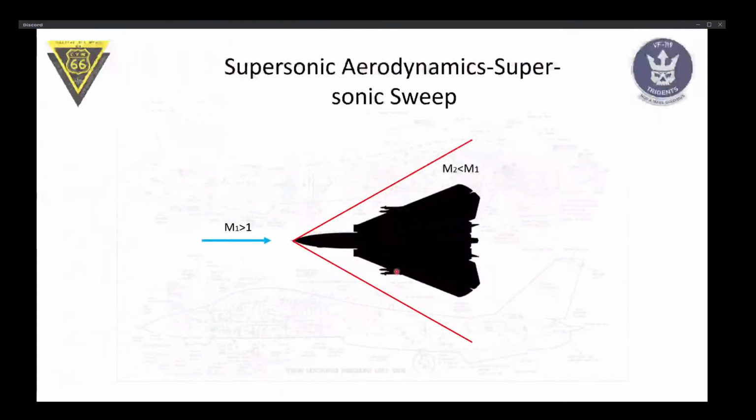That's basically it for the supersonic aerodynamic introduction. Just to reiterate, we have this wave drag, and to reduce the wave drag, we are sweeping the wings back to reduce the effective component. And also in supersonic flight, we have this oblique shock, which further reduces our Mach number.